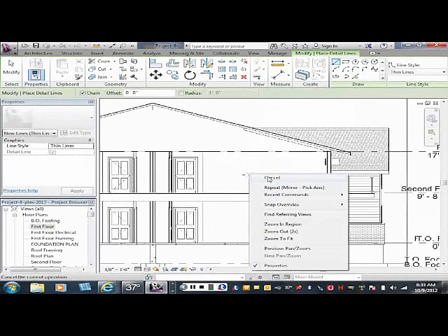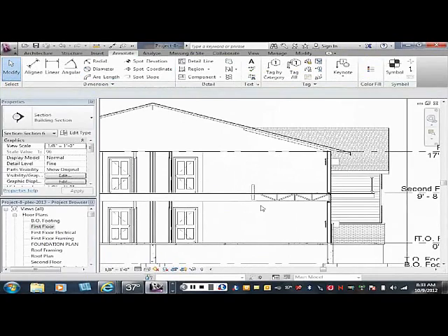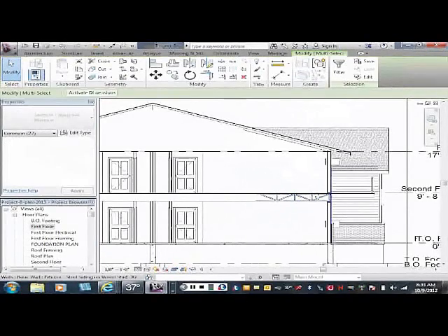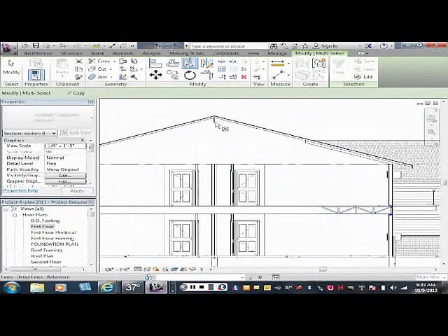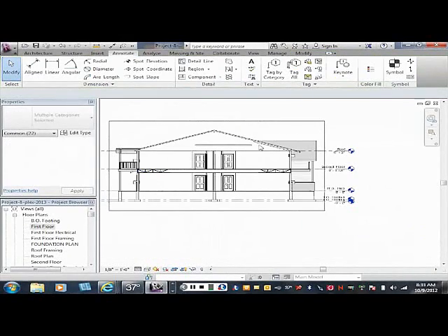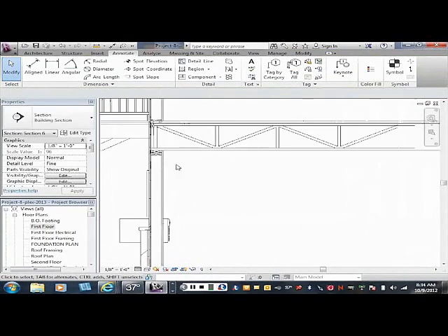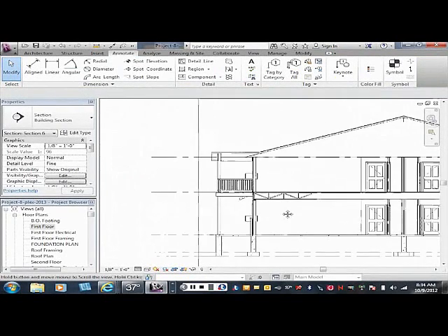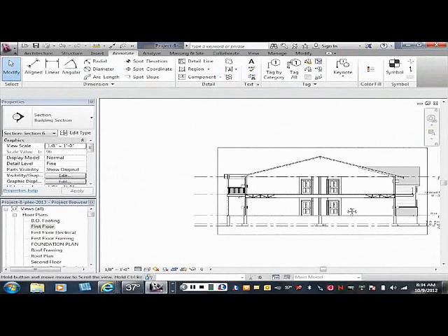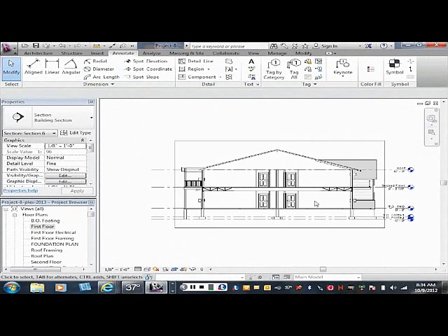So that's just a construction line, a temporary line. Then I'll go back and copy that stuff with just a copy command. Then go to mirror it off of that line, and I put it over on the other end of the building. So that might be all we need for the detail of this building, of that floor truss, right?